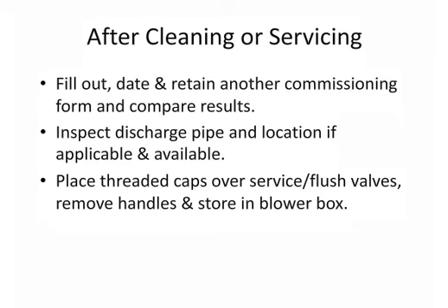I usually would place threaded caps over the boiler drains that I used for the service and the flushing. And I remove the handles and put them in the blower box of the heat pump because, well, I just didn't want homeowners or their 5-year-old boy giving his Tonka toy a good washing. So that's just what I did to prevent monkeying with it other than the professional serviceman.